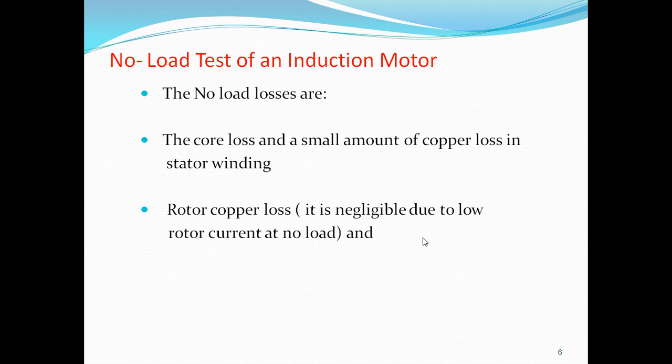The rotor also has losses. It is negligible due to low rotor current at no load, and friction and windage losses. So no load losses contain these things: core losses and a small amount of copper losses in the stator, rotor losses, and friction and windage losses.